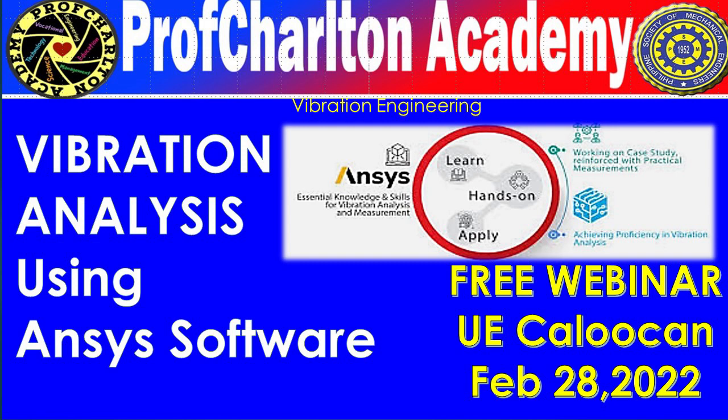And we have print simulations. Using the print simulation software solution, you can take the part and define the printing parameters, the machine parameters, like the laser speed, the layer thickness, and hatch spacing. All the real-time printing parameters can be set in the simulation, and you can run the simulation and check what the stresses will be after printing, what the distortions will be, or whether the support will fail or not. All these different aspects can be simulated.